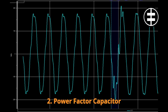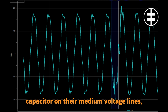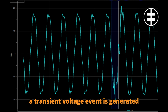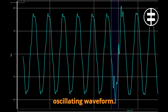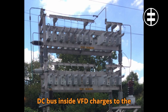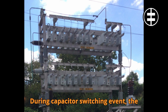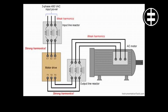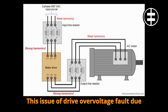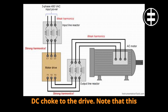2. Power factor capacitor switching. When an electric utility switches a power factor correction capacitor on their medium voltage lines, a transient voltage event is generated with a characteristic low-frequency oscillating waveform. DC bus inside VFD charges to the peak of the AC input voltage value. During capacitor switching event, the higher input peak voltage can temporarily boost the DC bus voltage and trip on overvoltage fault. Solution. This issue of drive overvoltage fault due to utility capacitor switching can be prevented by adding a line reactor or a DC choke to the drive.